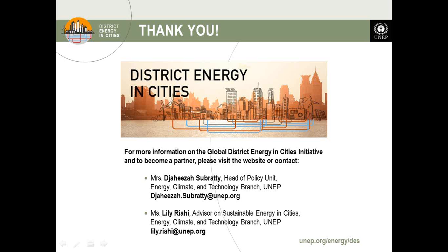But what's important about this is that they don't look only at the building, but they look at the supply of heat and hot water. And so these standards can be met by connecting to their district heating network in combination with building efficiency measures. This is really one of the best practices we see in building codes that look at primary energy efficiency, and therefore incentivize fuel switch in district energy systems as well as demand measures.